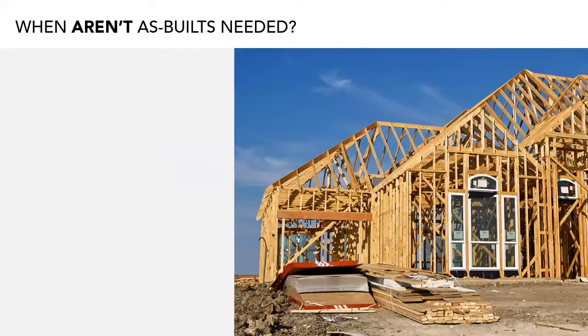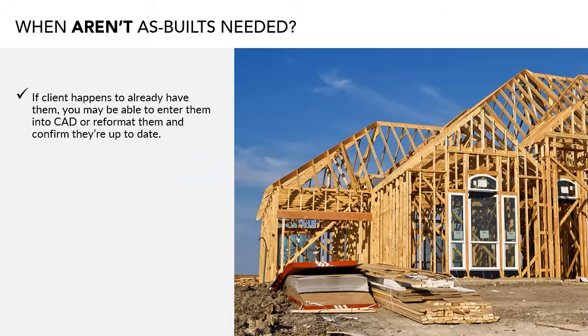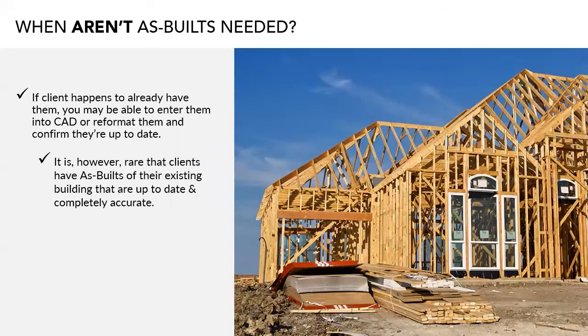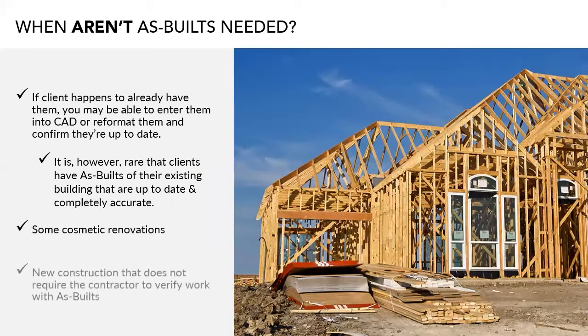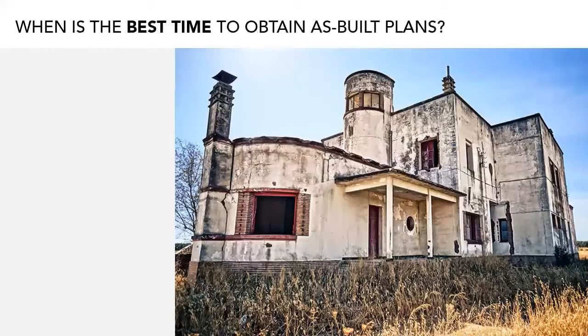And then what are some contributing factors when as-builts actually are not needed? It is rare that clients already have current as-builts of their existing buildings that are actually accurate, but it does happen. And in that case, of course, you would not need more as-builts before starting your project. There are also simple cosmetic projects that do not require having accurate as-built plans. And of course, if a building is being built from scratch, then all you'll need are those construction documents.